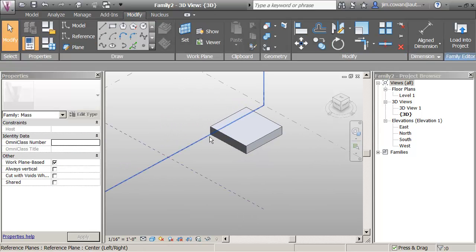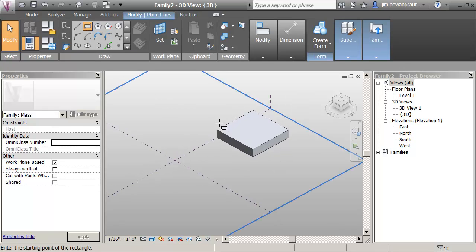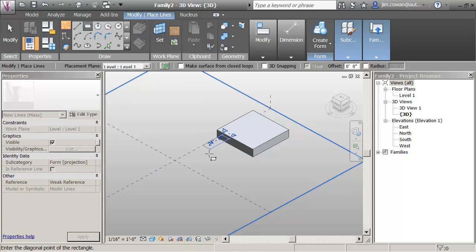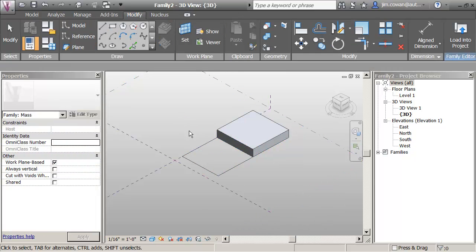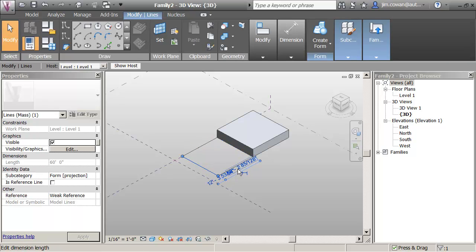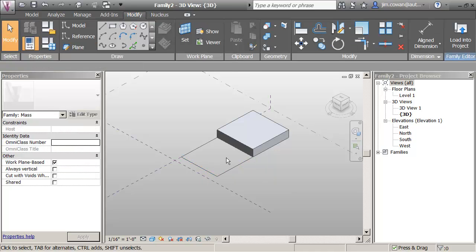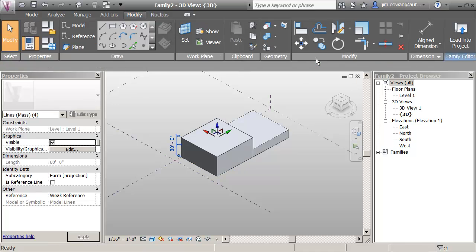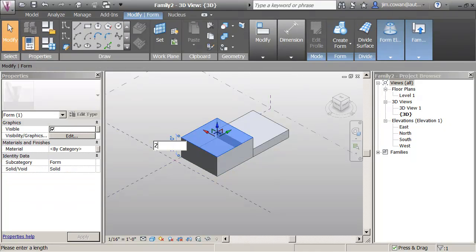I've got a gymnasium or assembly hall, something in front of it here. What I'm going to do is draw the shape. Always make sure that you refer up here where you're drafting, and make sure I've got this switched off. Click and click, and I was able to align that here. If I double click on here, I'm going to set that dimension to being the 60. I'm going to do my extrusion of the shape, the create form, and I'm going to set the height to 24.